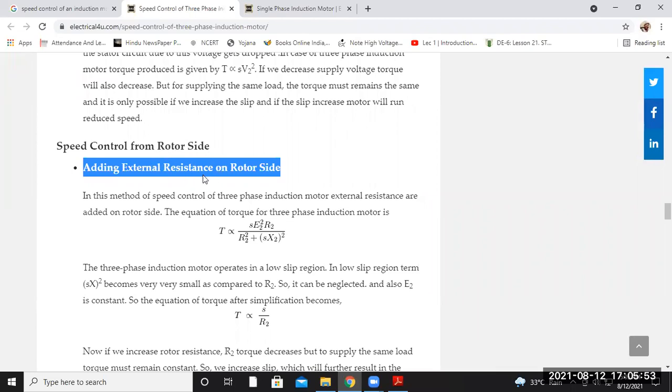If the flow of current decreases, the torque developed will also have a lesser value. That means if the rotor current decreases, the speed will also decrease. In the starting condition, all the resistance that we have added in the rotor part is connected in series in the rotor circuit, so that less current will flow, and the torque, or you can say speed, will remain less.